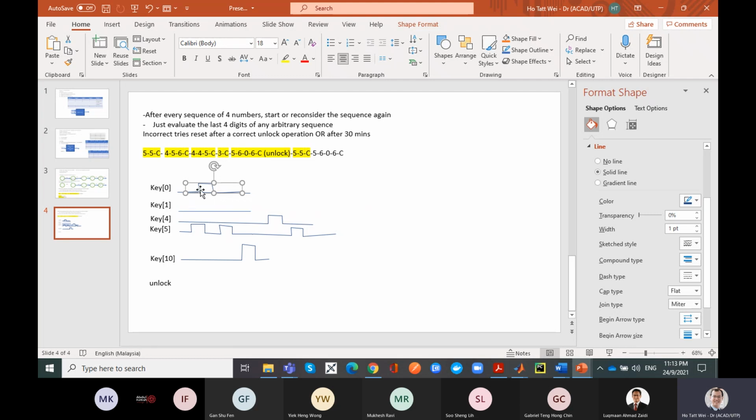Because you cannot just blindly assume they are not that way. The signal doesn't work like that, right? Say if you have a digital circuit, you are specifying these are your input pins, right? So when you design maybe the IC for this, these are your inputs. You can tell the designer, oh, okay, you can only press these in a certain amount of time, but what if the circuit that is inputting to your circuit doesn't obey that? Then will it really screw your circuit up? Right? So you have to consider that.